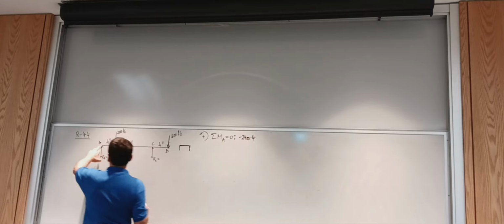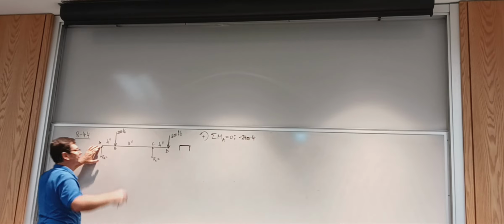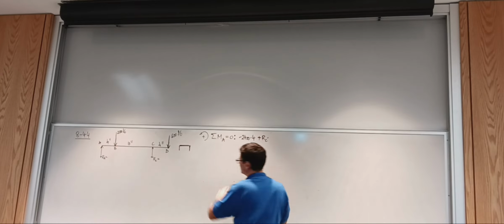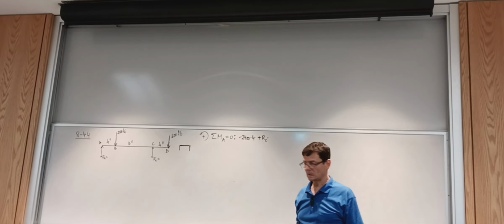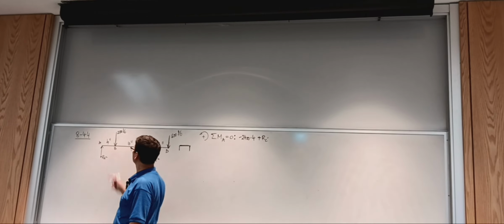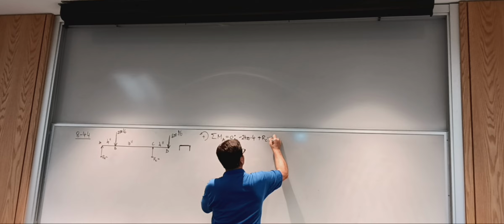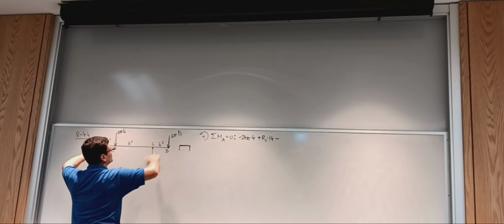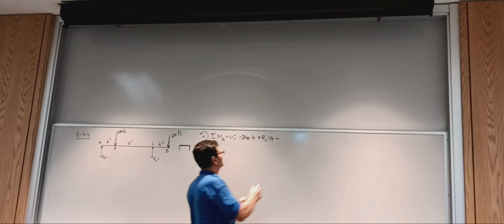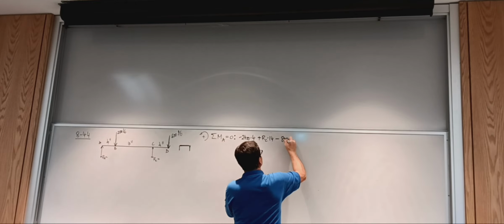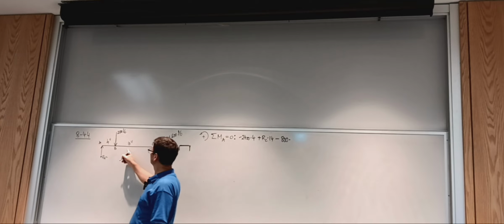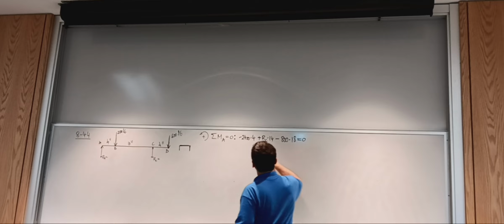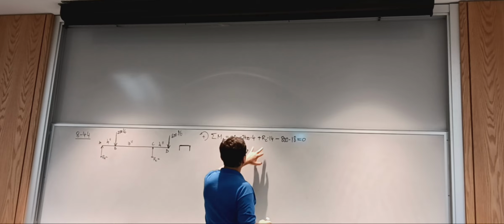Then I have RC, a positive moment, times the arm, 4 plus 10, 14 inches. And then another negative moment due to the 800 pound force, 800 times the arm of 18 inches, equals 0. So I can solve for RC now.